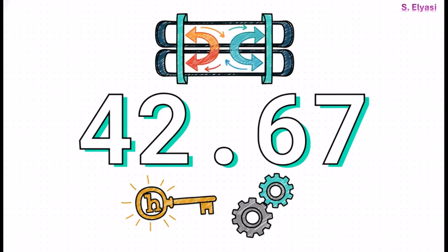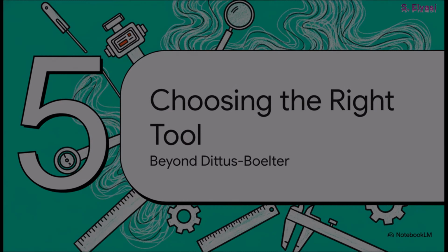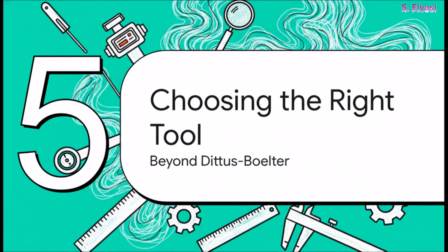So, what good is that? I mean, it's just a number, right? Well, this is the key. Because we know how the Nusselt number is defined, we can easily rearrange the formula to solve for h, the convection heat transfer coefficient. And that little h, that is the absolute golden ticket. It's the number you need for pretty much every practical heat exchanger design out there. So Dittus-Boelter is amazing. It's a workhorse.